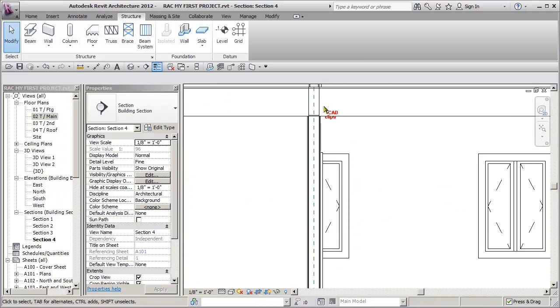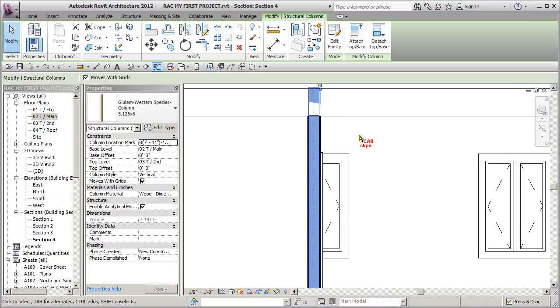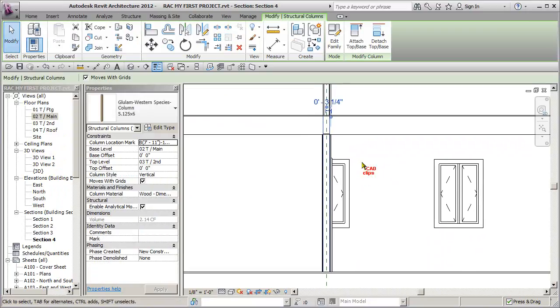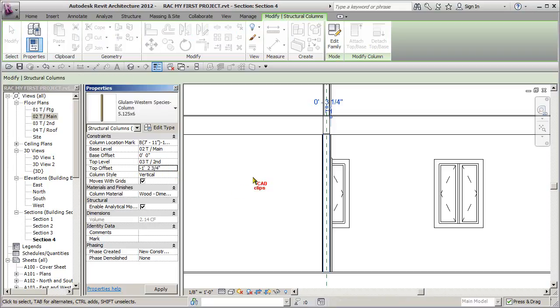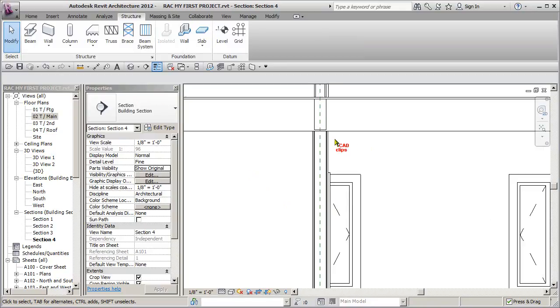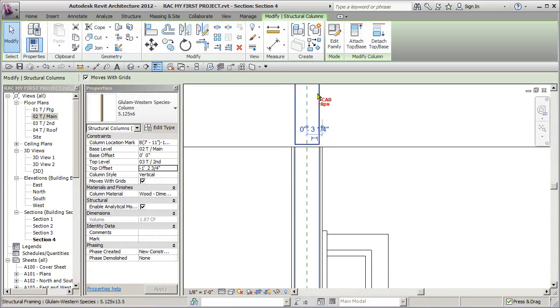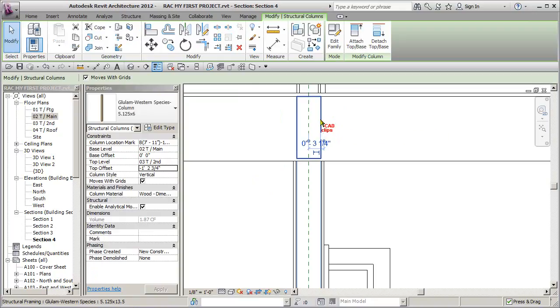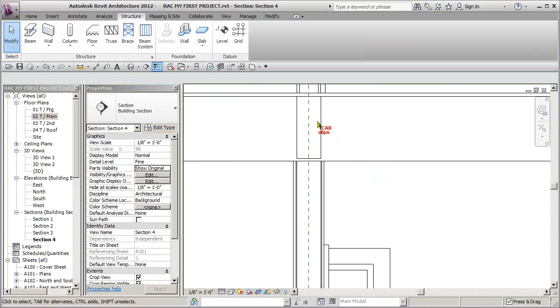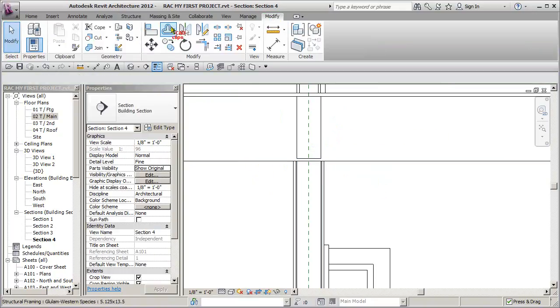Hover, structural column glulam. There it is. Okay, so what we want is from top of main up to second floor minus 14.75 inches, right? Boom. Click out, and now there's my column. In fact, this is not the full depth of 14 inches, so I wonder if I can use my align tool. Modify, align to here, this.